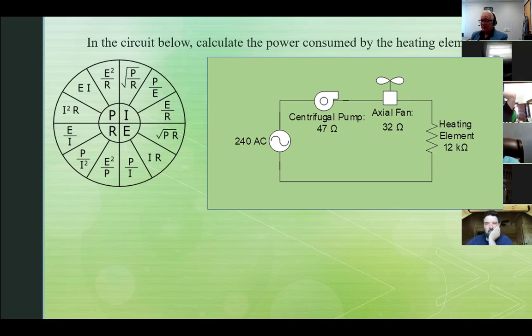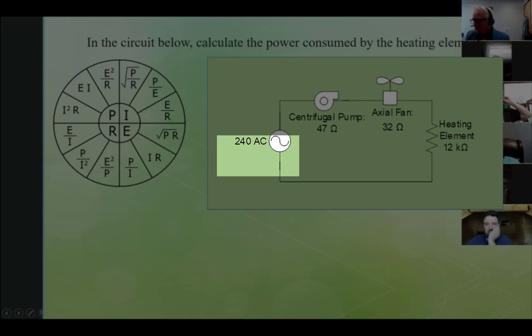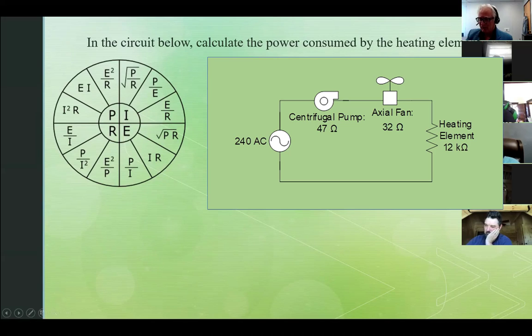Yeah, so to speak, you're right. Yes, in a series circuit, this voltage is divided up proportionally among everything in series. So yes, that 240 doesn't get there. Most of it does. And if I were a technician, I would probably just go ahead and, this is just a practical application. This isn't what you do for your test. For your test, I want exact numbers.